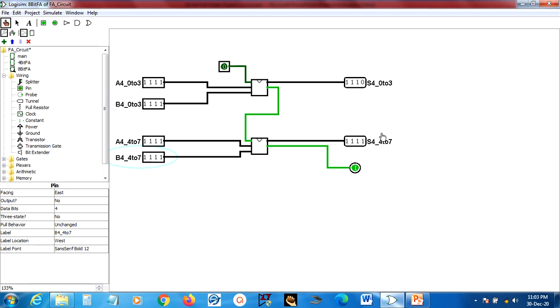Right, so this is the sum. Sum is 8 bits in length and there is carry. So you have to read like this: 1 1 1 1 1 1 1 0. Alright, so this is LSB and this is MSB, and this particular addition has generated a carry of 1. Alright, from two 4-bit full adder circuits, we could generate an 8-bit full adder circuit.